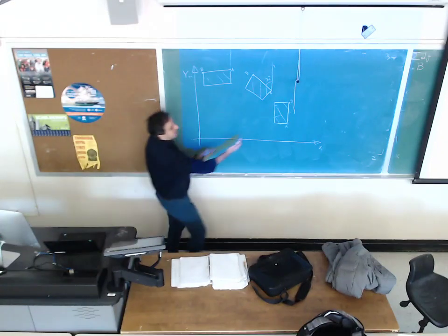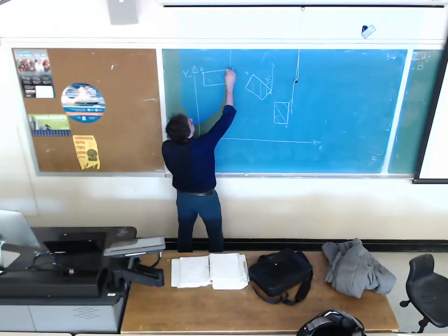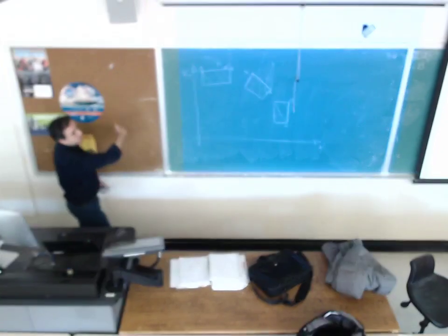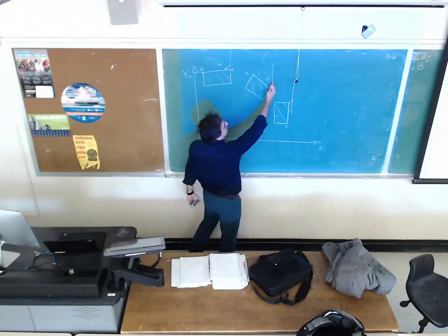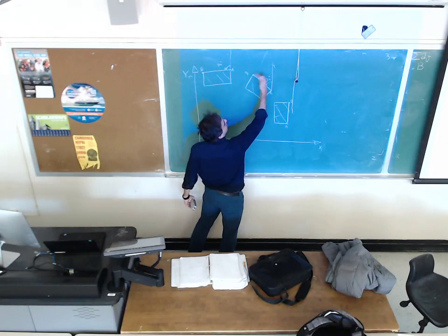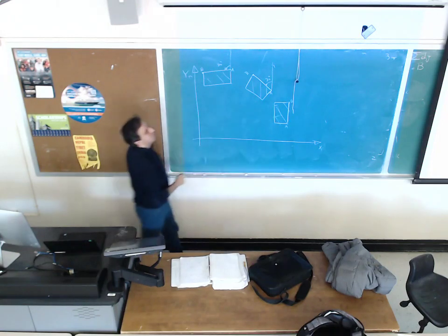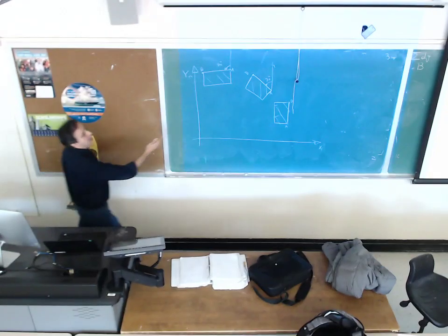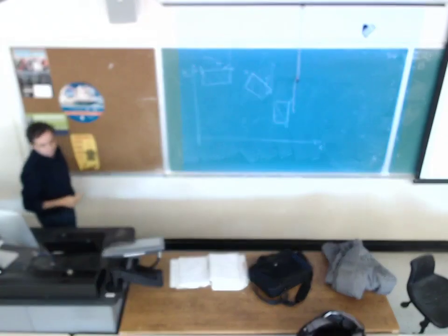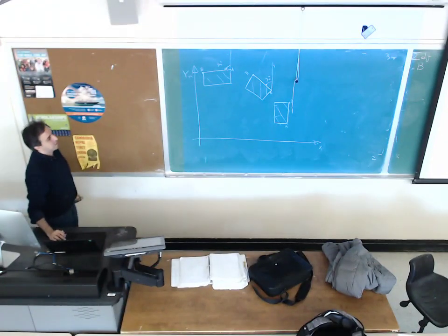And then this line has been rotated by the angle of 90 degrees. Since it's rotating counterclockwise, it's going to be positive. So this line from first precision point to the second precision point has been rotated by 30 degrees. And from first precision point to the third precision point has been rotated by 90 degrees.